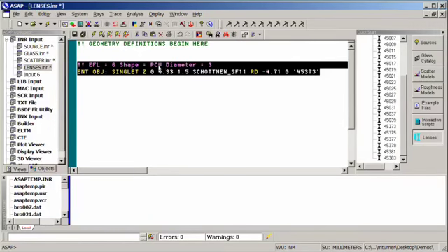In this case, it's a plano-convex lens with a diameter of 3 millimeters. It's a singlet, and in ASAP, what we're putting in here is the axis of orientation, the vertex location, shape factor information, the fact that it is made up of the Schott material SF11, the radius of curvature information, and the part number, or the name of the object, is the part number within the lens catalog.